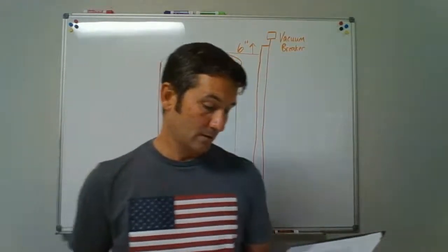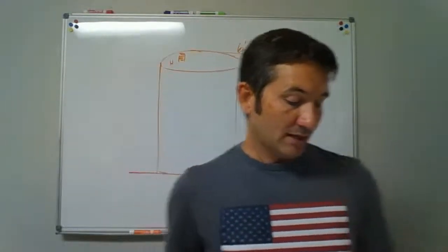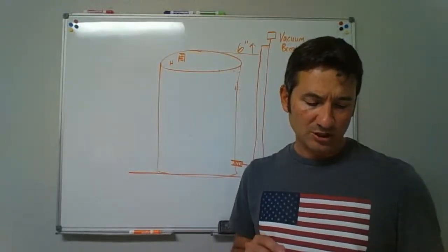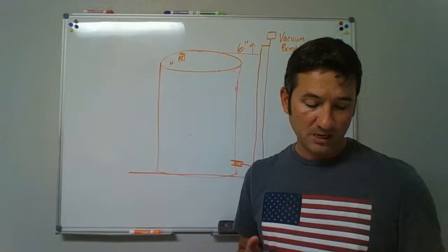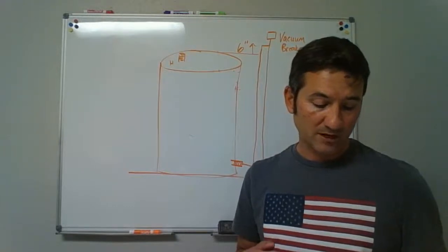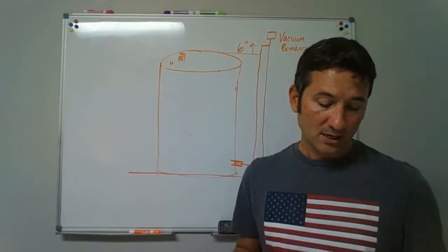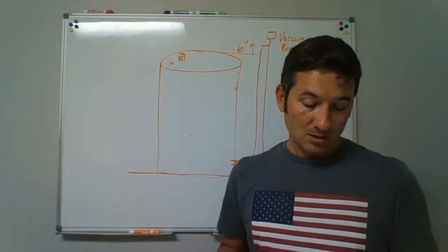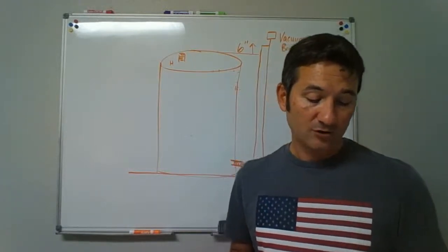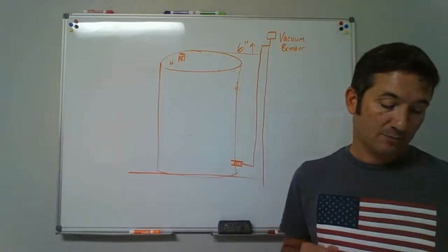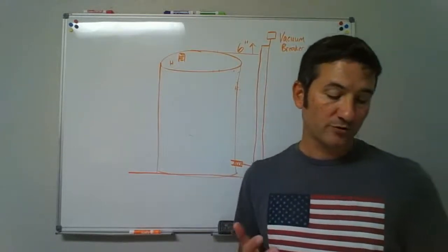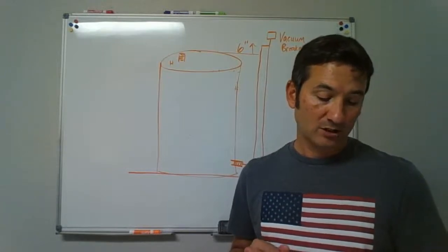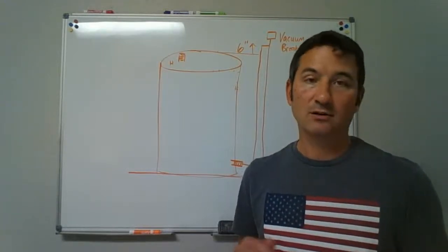Okay. Shutdown. A means for disconnecting an electrical hot water supply system from its energy supply should be provided in accordance with the NFPA 70. Separate valves should be provided to shut off the energy fuel supply to all other types of hot water supply systems. You have to have a relief valve. Storage water heaters operating above atmospheric pressure should be provided with an approved self-closing levered pressure relief valve and temperature relief valve or combination thereof.